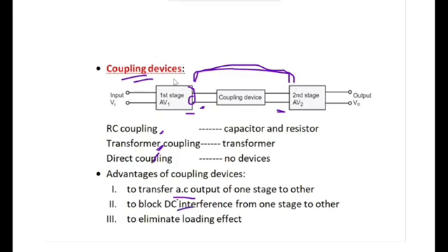We use some DC biasing at every stage of the amplifiers, and these are multi-stage. So the DC biasing voltage of the first stage may affect the second stage, or the second stage may affect the first stage. These effects will produce adverse effects in the amplification of the original signal, so it is required to block the DC interference, which will give a good output.